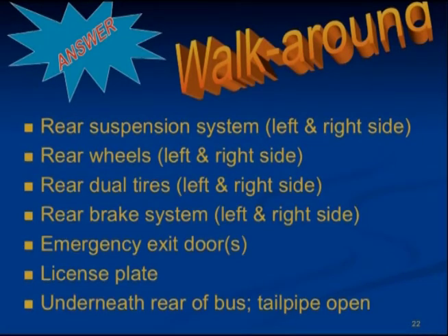Check the rear wheels and wells. Wheels show no excessive corrosion, cracks, or other damage. Rims have no welding repairs. Make sure that the lock rings are secure, the lug nuts are tight, the spacers, if they're equipped, are not bent, damaged, or rusted through. Look carefully at the inner wheels for evidence of wetness, and check the outside center axle seal for leaks.